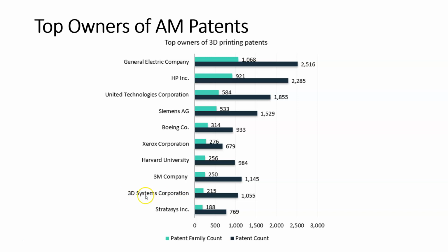That was the Charles Hull company that was started first, and then Stratasys was the company started by Scott and Lisa Crump. Remember, 3D Systems started with stereolithography, so a vat photopolymerization process, or resin process. And then Stratasys was started with fused deposition modeling, which is a plastic 3D printing process, material extrusion.